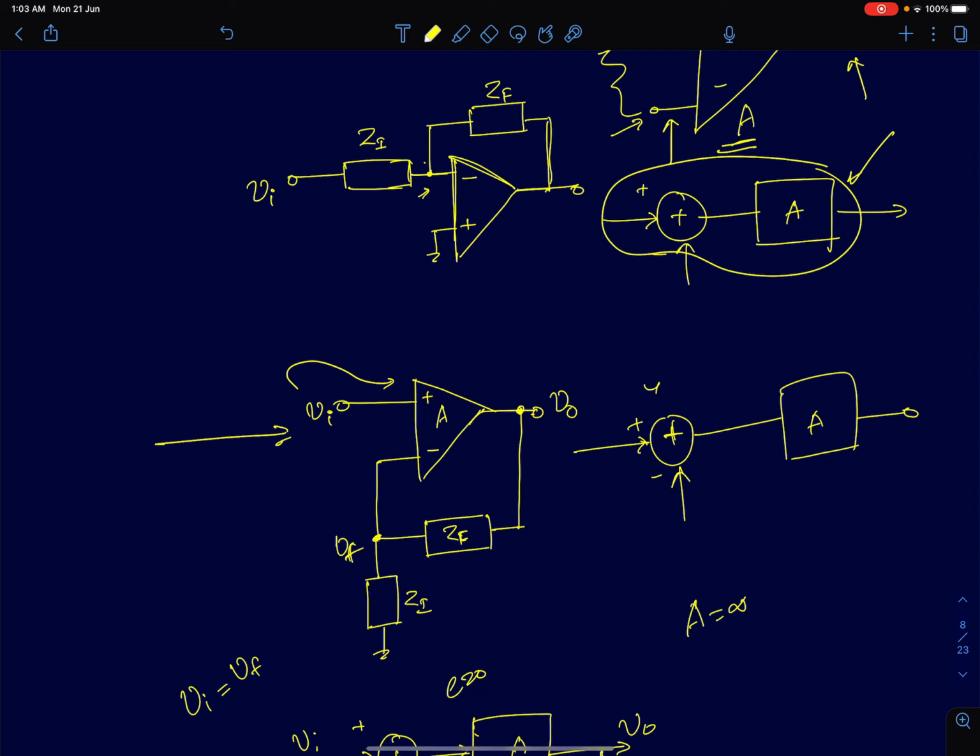In the previous course on microelectronic circuits, we already discussed how to break a loop and find the loop gain. We can do that for both these circuits. The loop gain will be the same for both the circuits, and we can also instantly see that both these circuits have negative feedback. If I break the loop at this point, and traverse and return to the same point, we can immediately see that the loop gain will be negative, which means it's a negative feedback. I can apply a similar procedure here. I can break it here and return to this point.